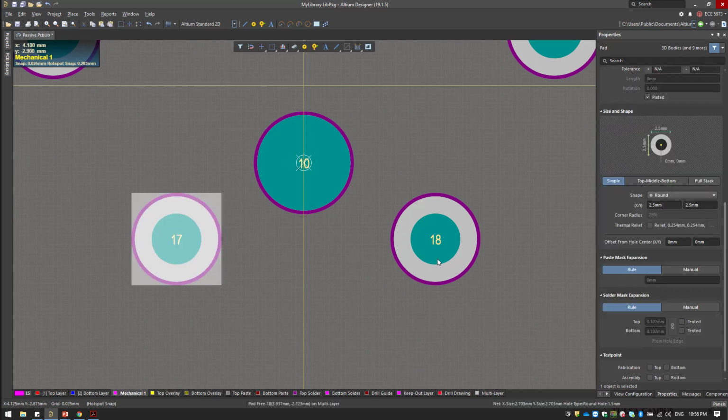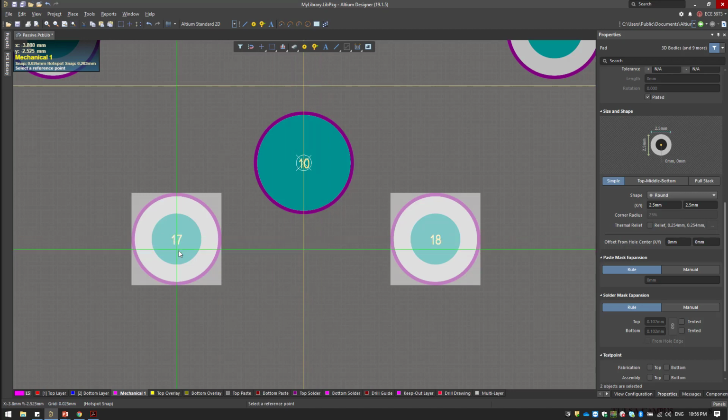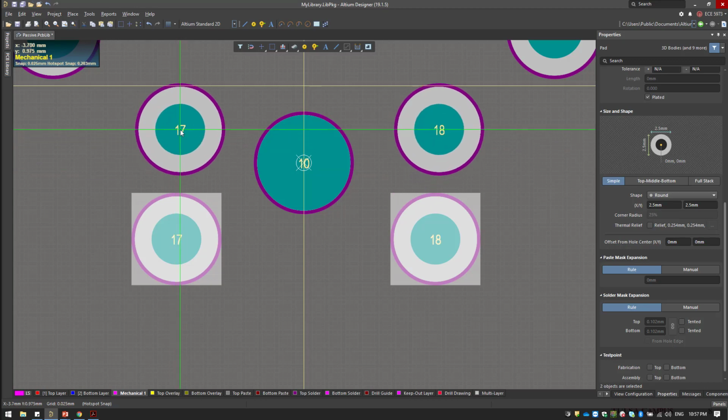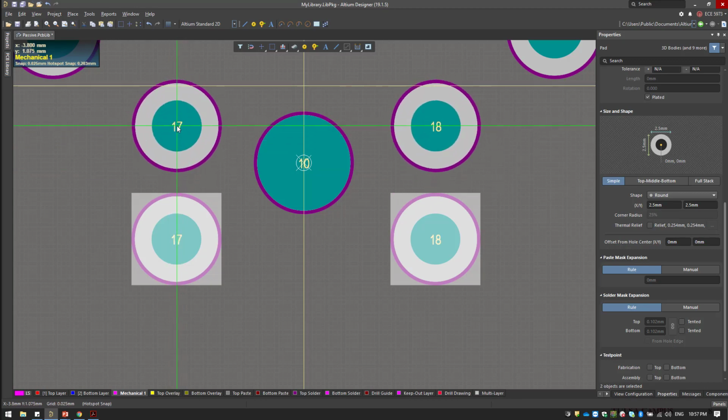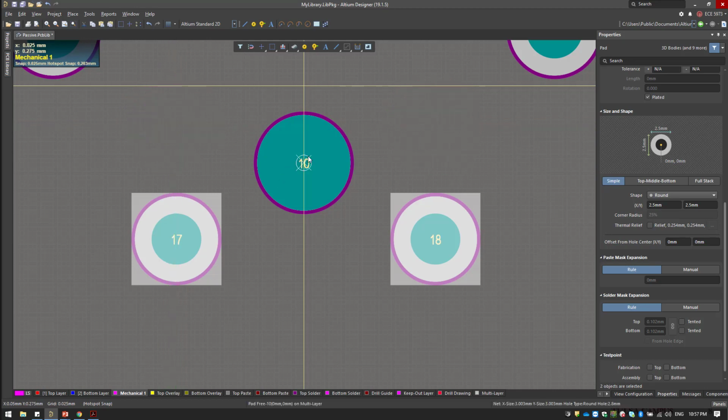Now we need to copy these two, Control C, and when you copy, you need to select now the reference where if you click on here, now when you Control V, paste them, the hold point, the handle will be at the point you selected. So in this case, it's better to have your origin point as the handle. Why is that?